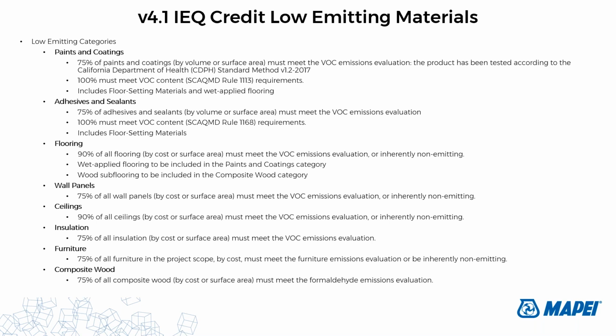So ceramic tile, you would just simply have to check a box that says the product is inherently non-emitting, and you wouldn't have to go through the effort of finding VOC emissions certification testing unless one's been done. Wood subflooring is included in the composite wood category.